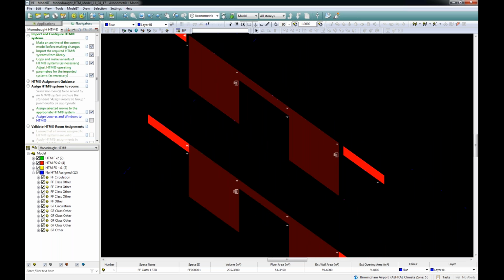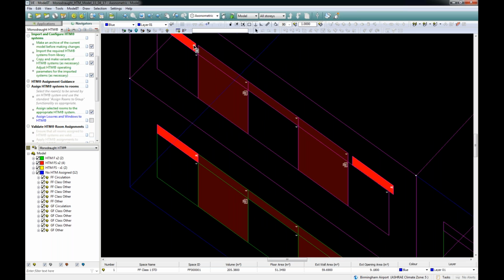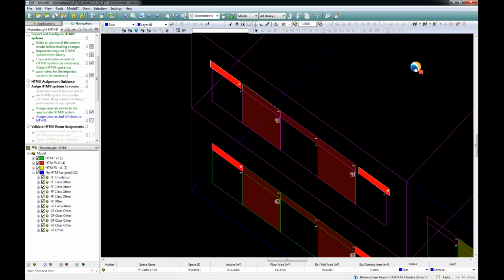And if you look closely, once you do the selections, the little icon where the drop-down arrow is located will also change, just to help illustrate the differences that have been selected. So you'd have the supply air coming in, showing the arrow going into the room, and then for a typical exhaust, you then have an arrow pointing out. But for this, as we've got the FS units, we change that to integrated louver.